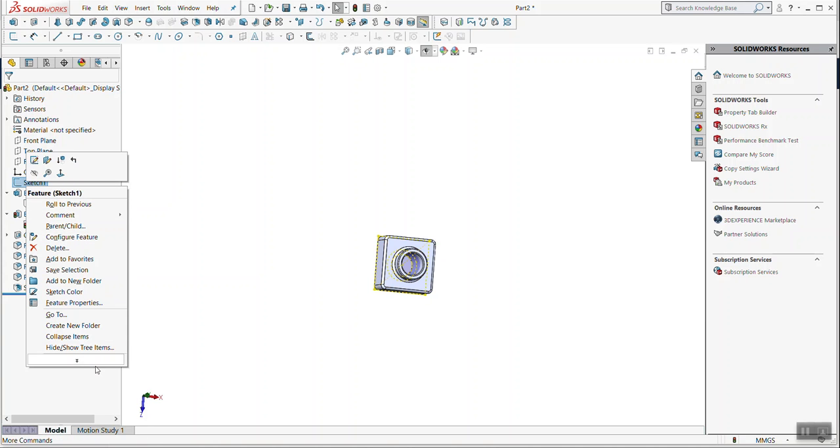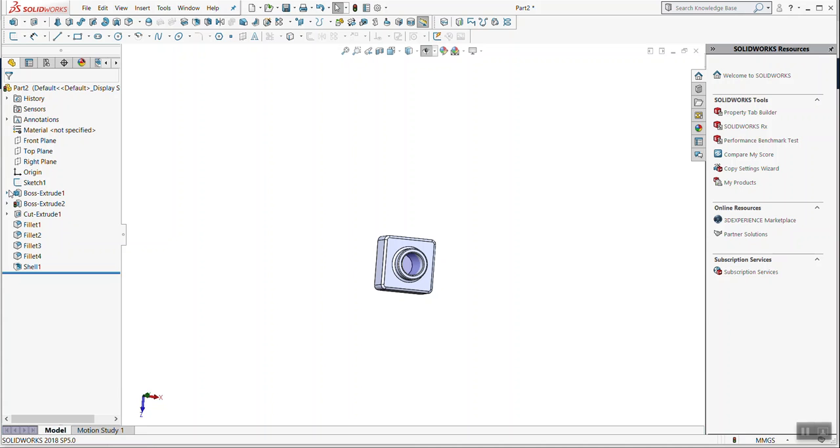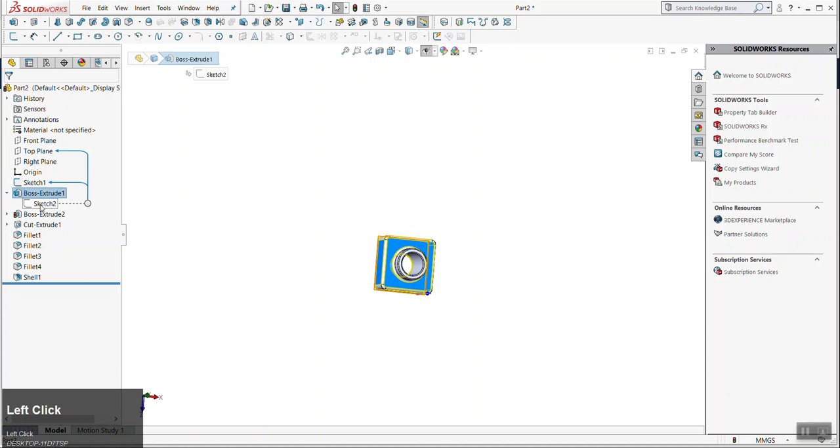Now, I was also recently told, and this isn't my style, and again, I'm teaching you guys my workflow. I'm not claiming it's the best. And again, there is nothing best. Everyone's going to find something that works for them. Apparently, there is a new setting in SolidWorks in the last 2 years where you can have it not eat sketches. Some people may prefer that. I think that's how Pro E works. I don't know, but that would confuse me because it is a pain that it eats the sketch, since the sketch kind of disappears. It is nice to know that if I go to this feature, I can see the sketches underneath here if I need to edit it.